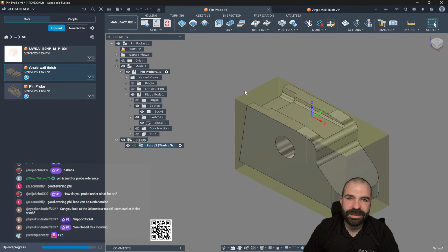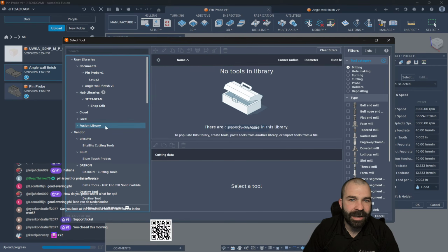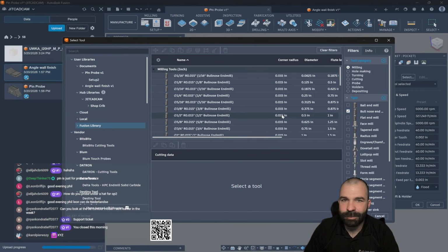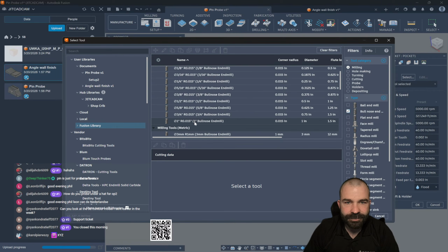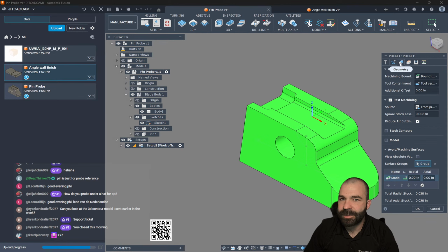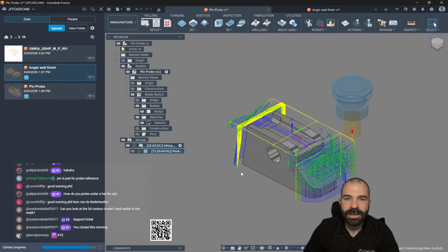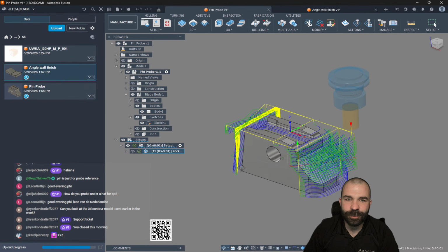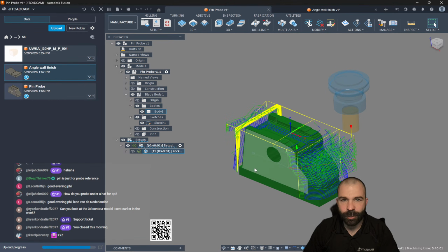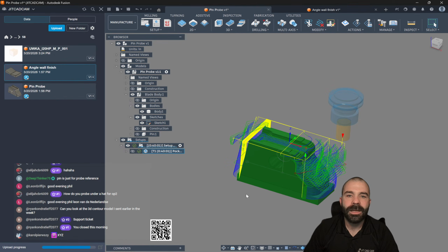Basically speaking, anybody out there that doesn't know, let's say, for example, you're going to rough out this part. I'm going to use 2D pocket clearing. I should have a good old fancy bull nose. Let's just say you're using like a 1-inch kind of tool. This is a pretty good size part. No boundary. What I'm looking for right now is we want to go ahead and get that outside all cut away. And now I'm stuck with a hat when I flip this part.